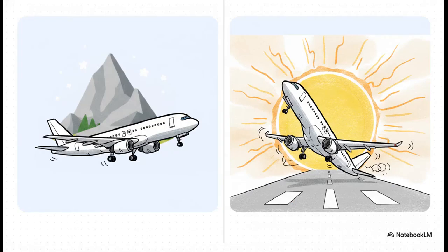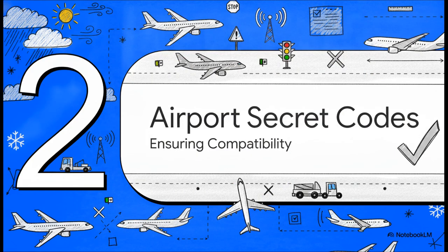To break it down simply, true altitude tells you exactly where you are on a map, your literal physical distance above sea level. But density altitude tells the aircraft's engines and wings how well they're actually going to perform in the current weather. If the density altitude is high, your aircraft's performance is going to be low. It means you're going to need way more runway to get airborne, and your climb is going to be super sluggish. Pilots rely heavily on this critical calculation to know exactly what the plane is capable of on any given day.